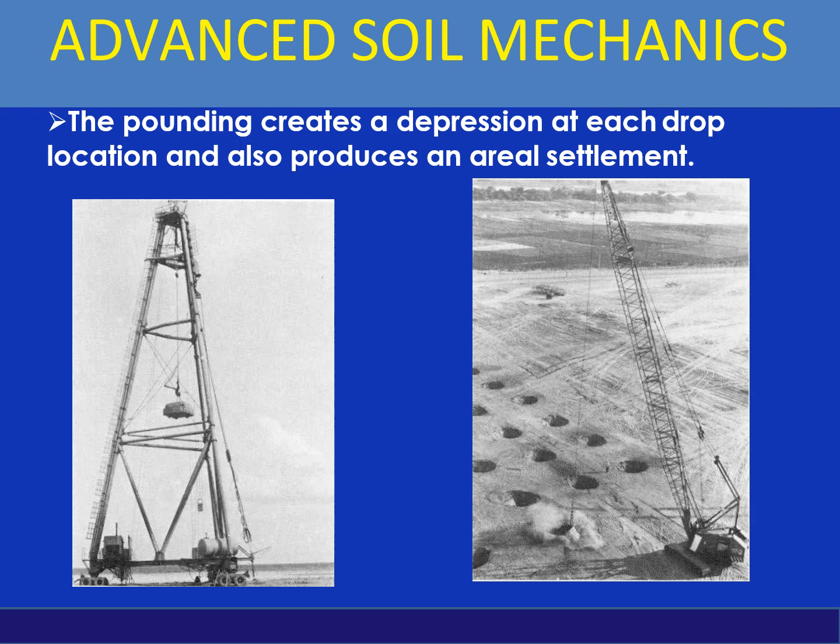And here you can see the arrangement that we are having for that pounding action. The pounding creates a depression at each drop location and also produces an areal settlement. So in this way, these heavy weights will be dropped and this whole area can be compacted.